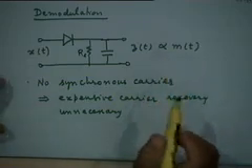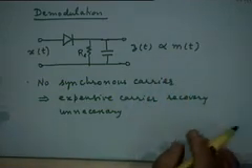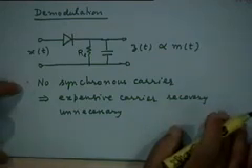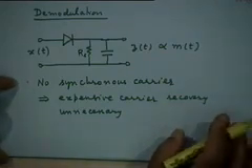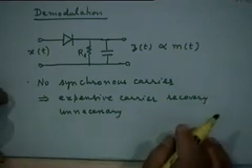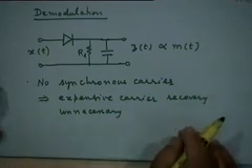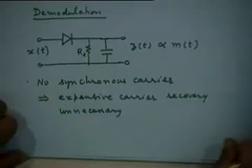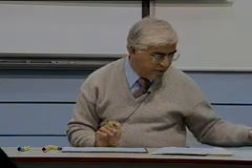Right? And if this works, as we indicated briefly how it could, the advantage of this simple circuit is that we don't require any complex circuits for synchronization of the local carrier with the incoming carrier. So no synchronous carrier is required, and thereby the receiver becomes a much cheaper version.